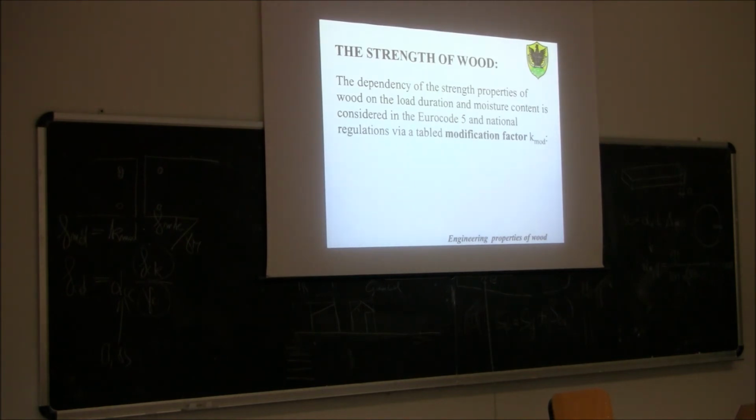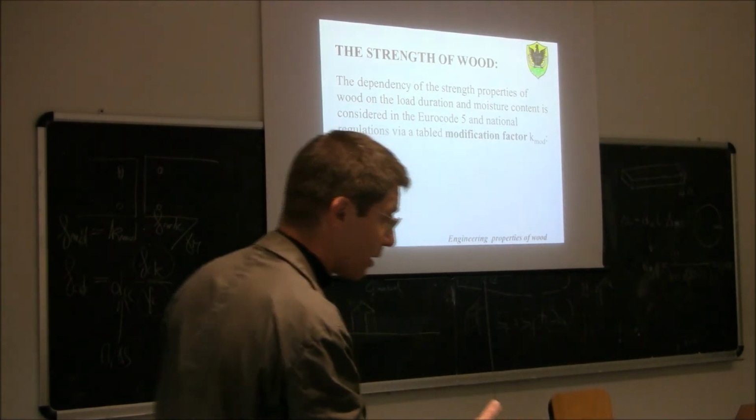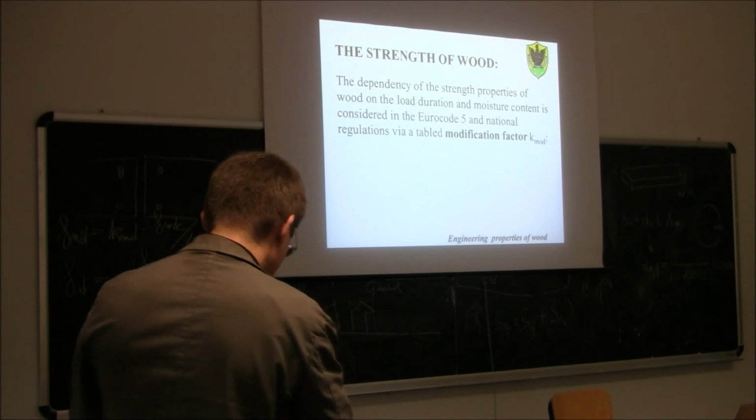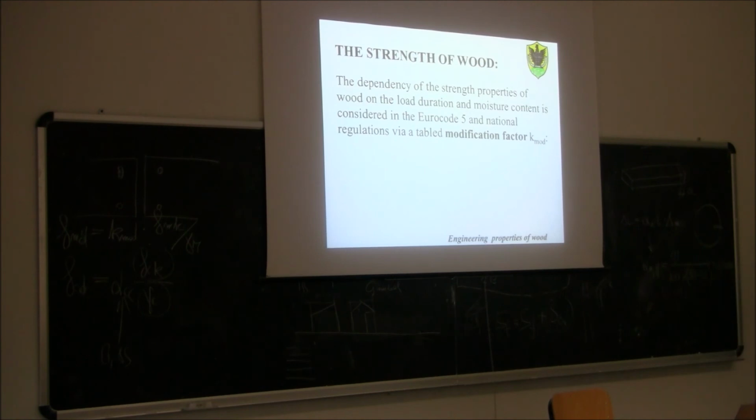You remember before we said that the strength is affected by the moisture content. Remember, we said that the higher the moisture content, the lower the strength. So, how can we take into account the effect of moisture content on strength? It's all accounted for with this same coefficient K mod. So, K mod basically takes into account two phenomena. One is the dependency of the strength on the load duration, and the second is the dependency of the strength on the moisture content.